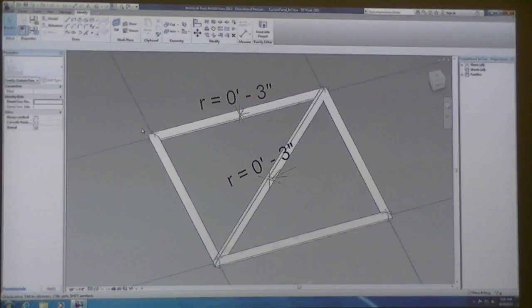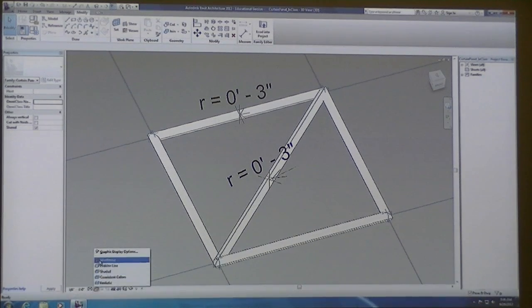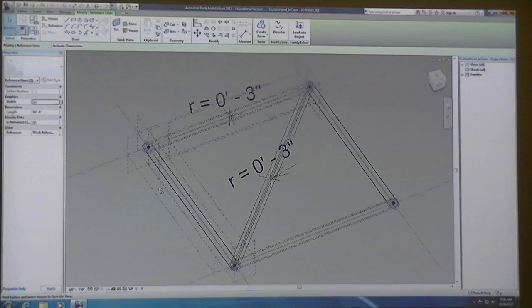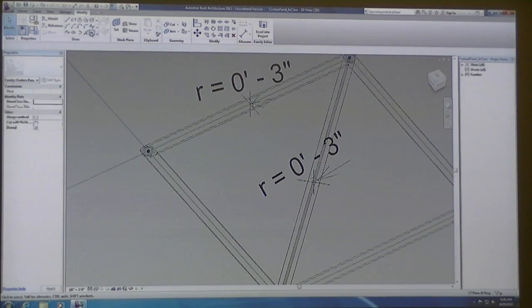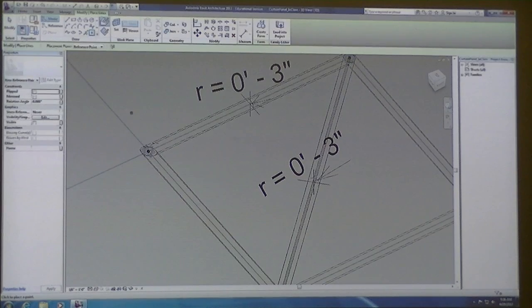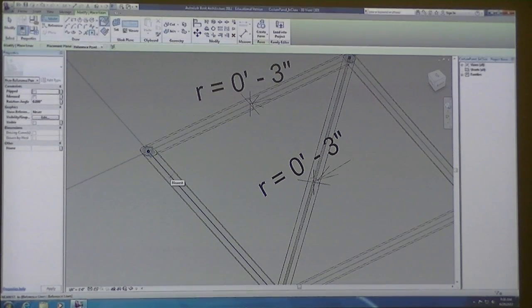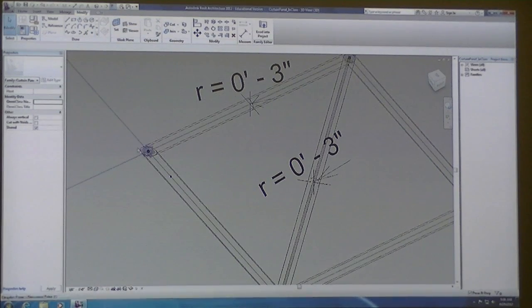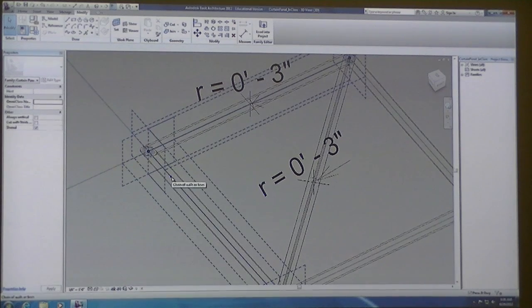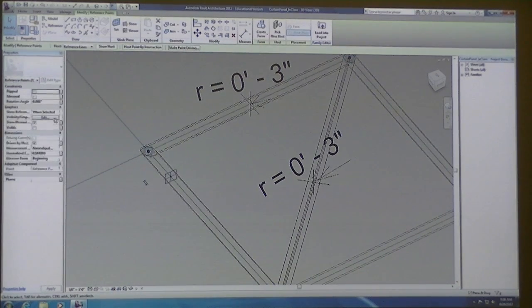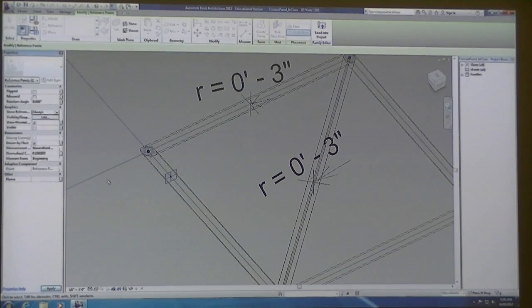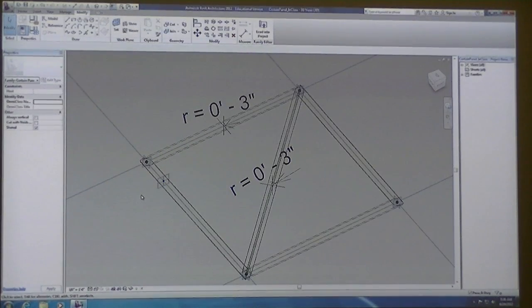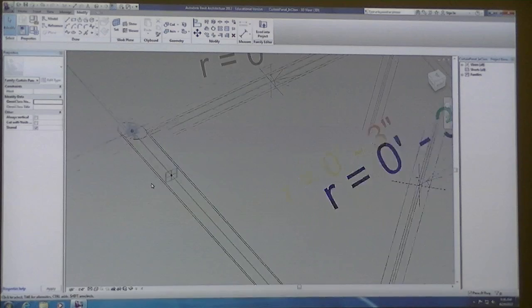And in Revit, in order to make a sphere, it's a little bit tricky, but I'm going to go back into my wireframe mode. And I want to host a point, so I'm going to pick the point element and host a point somewhere on this reference line. Doesn't matter which line you pick, just pick one of them near the corner point. Next I'm going to tab over it and choose show reference always. I wish there was a default that would always turn that on, but unfortunately you have to do that manually each time.